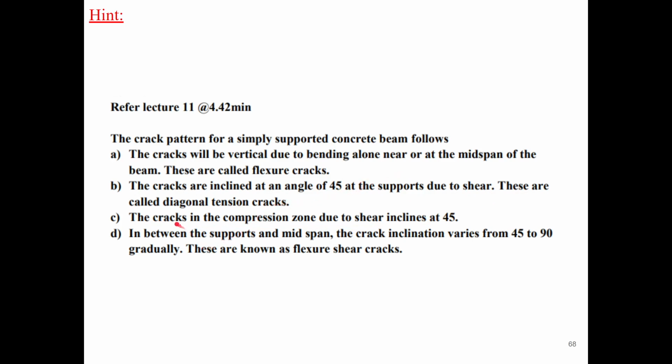Okay. And if the cracks occur in the compression zone due to shear, that also inclines at 45 degrees. Okay. And in between the supports and midspan, the crack inclination increases from 45 to 90, as we gradually go from the midspan to support. Okay, sorry, from support to midspan.